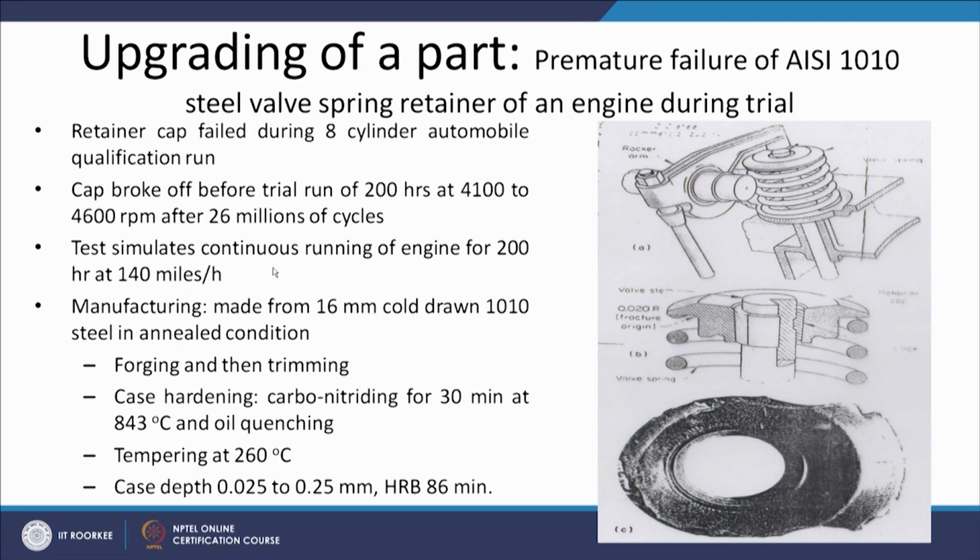The retainer cap failed, and the cap was made from 16 mm cold drawn 101 steel. This is a plain carbon steel having 0.1% carbon. This is the AISI designation of the steel, and it was in annealed condition.